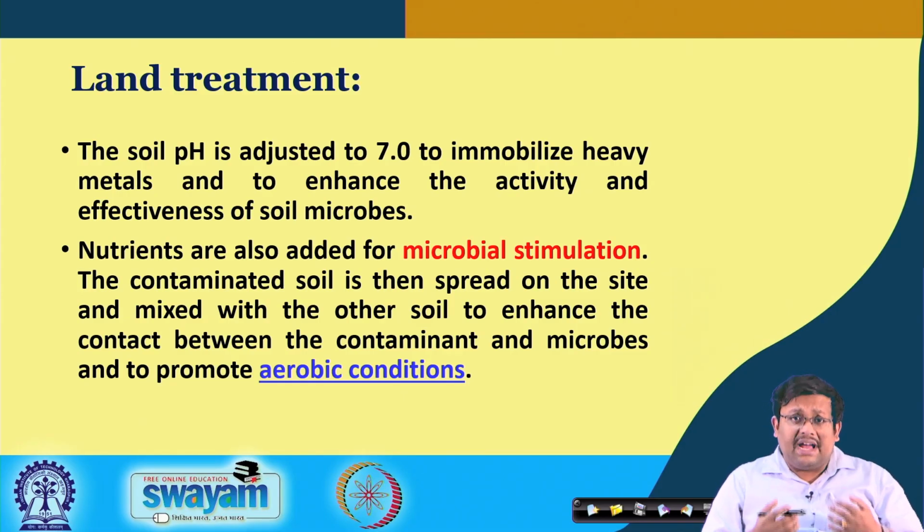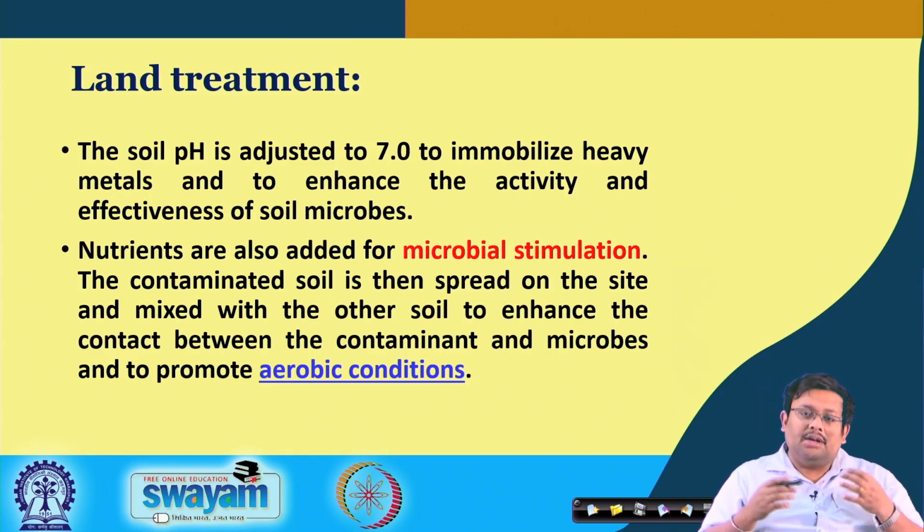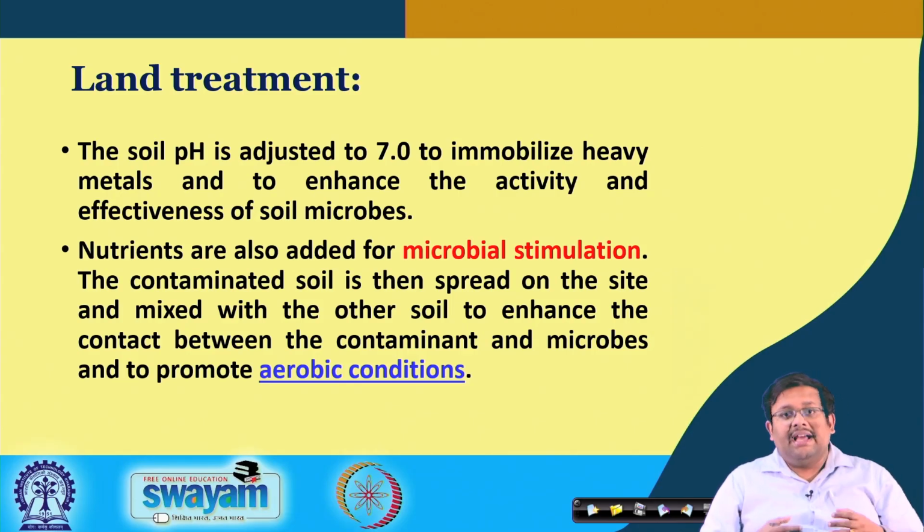Sometimes we also add nutrients for microbial stimulation, because when you apply the nutrients, that will help in microbial growth and then stimulates the microbial growth for further degradation process. The contaminated soil is then spread on the site and mixed with other soil to enhance the contact between the contaminant and the microbes and to promote aerobic conditions. The aerobic condition is needed for most of the microbes which are aerobic in nature, and by the stimulation process their activity is enhanced, and ultimately this enhanced microbial activity degrades the organic as well as inorganic contaminants.